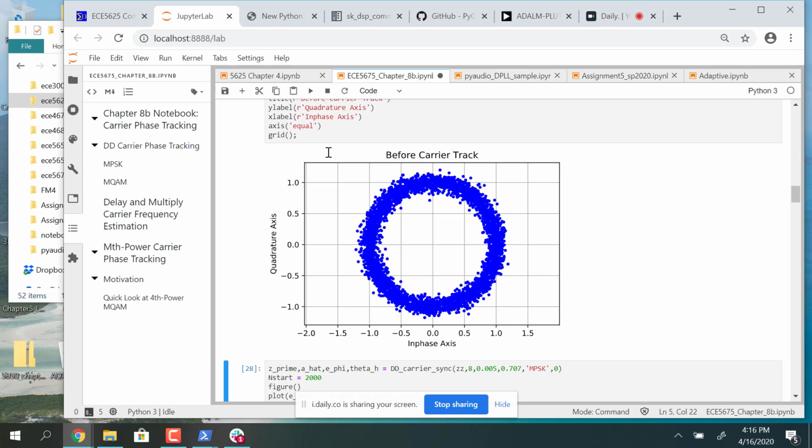I have this waveform, or this scatter plot I call a donut. The carrier signal is spinning around in the complex plane, and there's noise added onto it, and that gives it width. That makes it more like a donut. And phase modulation, like we've been describing, is used to send 8 different phase values.